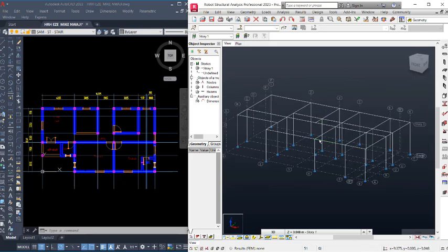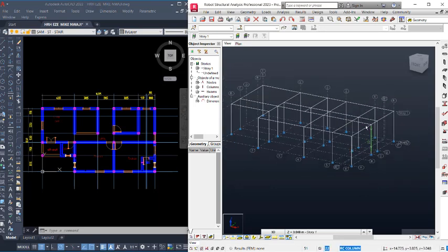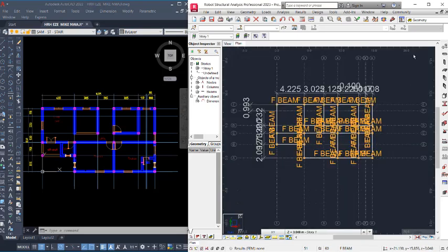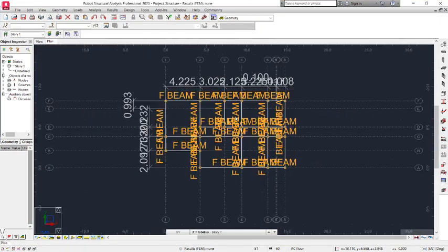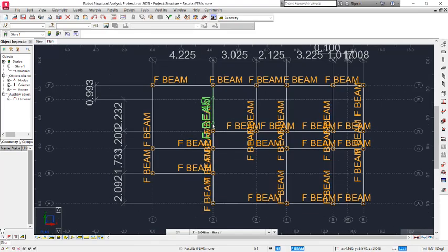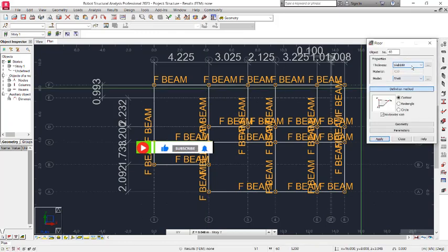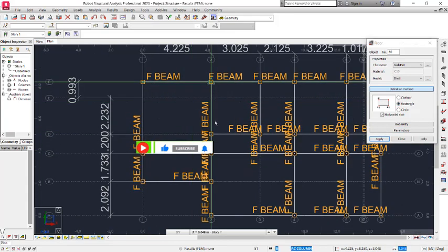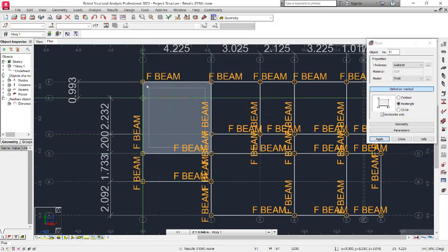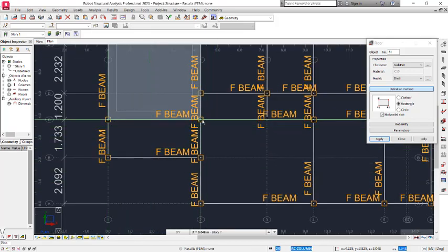All right, at this point we will be placing the reinforced concrete slab. So we navigate to the plan as well, and then maximize this and zoom in closely. For the RC slab, we come to the slab options right there. Okay, so we use shell. The slab thickness we will be considering is 150 millimeters. We can use rectangle right there, and then we pick this point to place the slab right there. You can see, right? So continue to place it successfully.